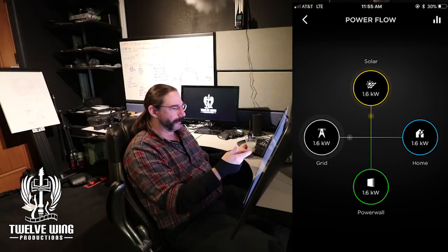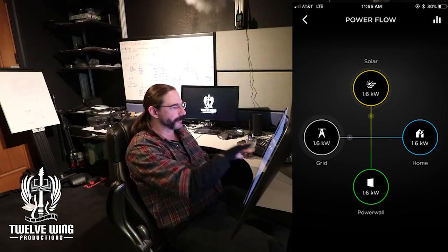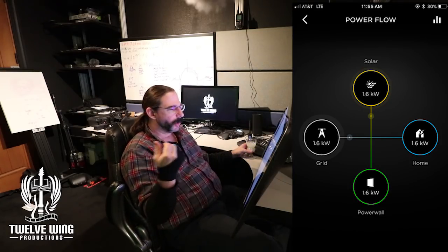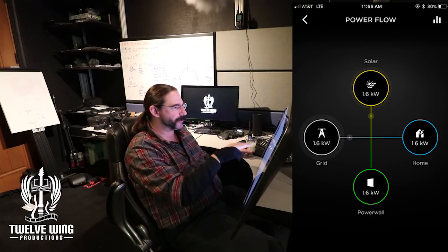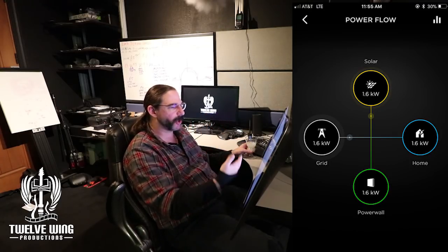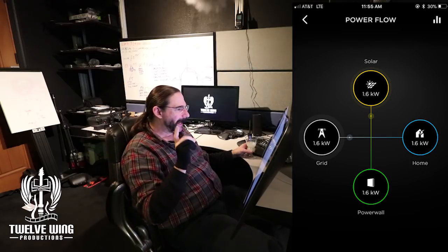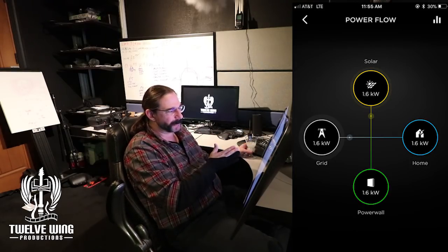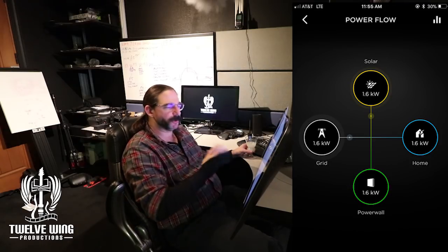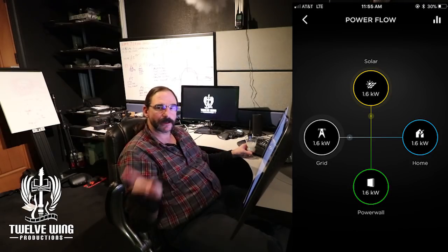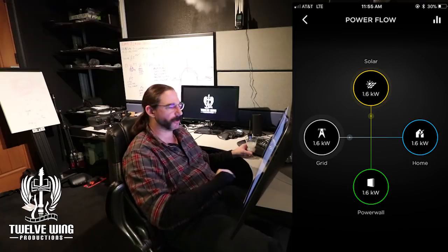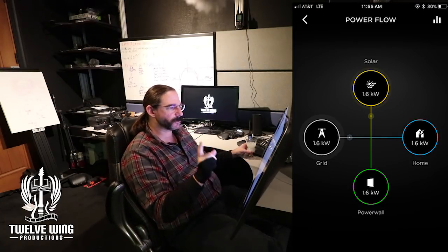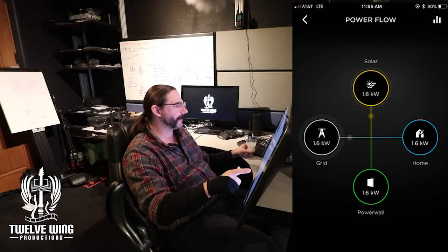Here's where that whole thing would have been interesting. It's nearly noon. We told the system that our off-peak rates end at noon. Like I said earlier, at the 10 a.m. screenshot, the system should have been charging at its maximum rate. Had it done so, even if we'd waited until 10 a.m. to make that decision, it would have put 20.4 kilowatts into the battery if it had been charging at its maximum peak. So now remember that 20.4 number. We'll get to that at the very end.